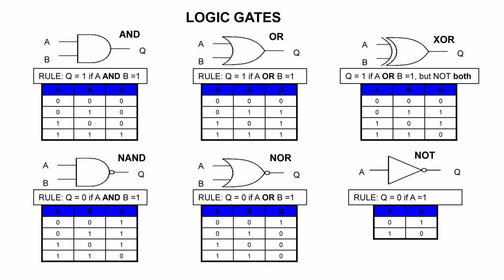XOR gate output is high when the inputs are not the same. XNOR gate output is low when inputs are not the same. NAND and NOR gates are called as universal logic gates. IEEE and ANSI support traditional distinctive shapes as well as rectangular outline symbols for the logic gates. Logic gates can be used in two basic applications, enable gate and inhibit gate. Logic gates are used in many household and industrial applications as well.